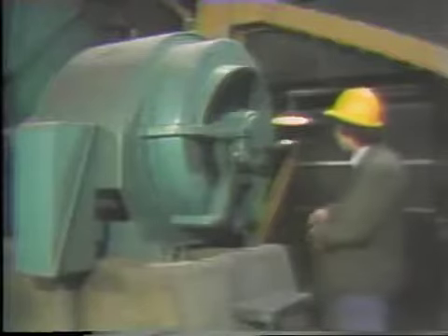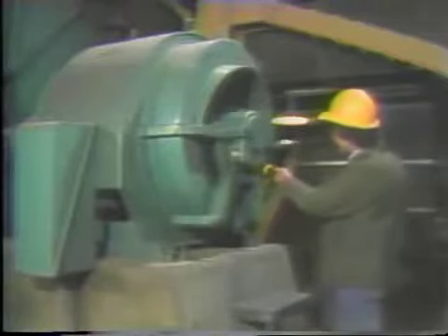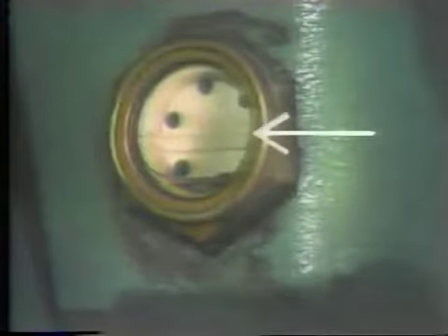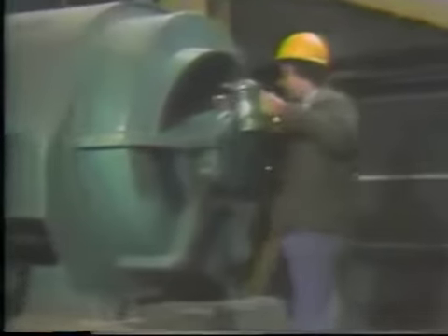Now, periodically, the oil reservoir must be checked. This is usually done by reading the level of oil on a sight glass. The normal indication would show oil halfway up the inside of the glass. If a sight glass is not present, the bearing might have a dipstick similar to the one in most cars. That will indicate the oil level in the reservoir. To fill the reservoir, oil is poured directly into it until either the sight glass or dipstick indicates a normal level.